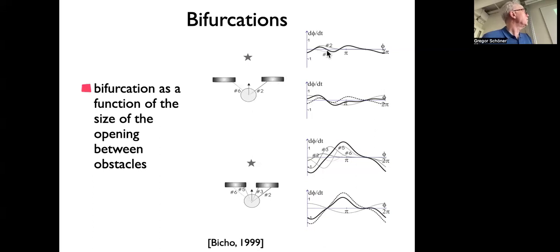And so this is the obstacle contribution. You see it's sort of a light gray. There's this one sensor and this six sensor, and they are far apart from each other compared to the width. And you see that in the middle, they don't overlap very strongly. So if you put a target contribution on top, this is the sum of all of those that can overrule. You still have an attractor here in the middle. Actually, between the two repellers, there is already an attractor, sort of the attractor from the side, right? The one force makes a repeller here, the other there, and there's an attractor in the middle. So if you add the target, you have a nice attractor in the middle.